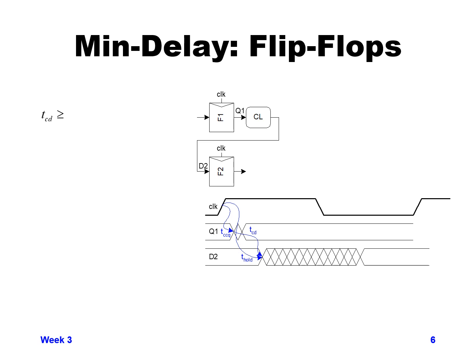And there's a certain amount of hold time, T hold, that the data needs to stay stable for at least that amount of time. And if it doesn't, then we could accidentally get that early data going through the flop when it wasn't supposed to.